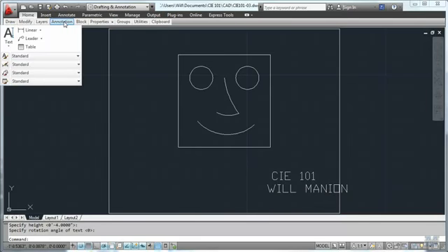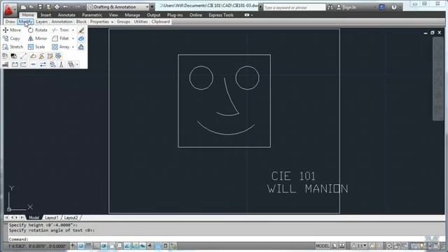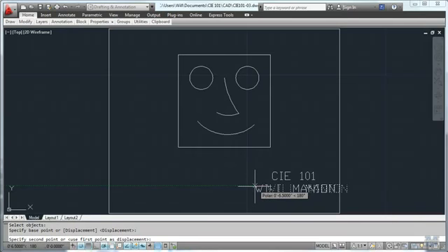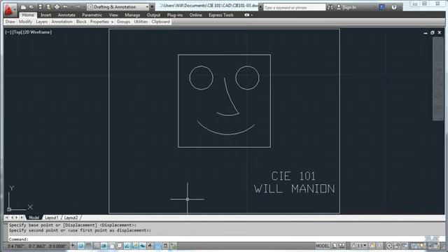So I guess I'm going to have to use the move to get that back on my screen. So let's go ahead and use the move tool this way. Select objects. I'm going to have to hit the enter key. That's the only object I want to move. Base point is where I want to start from. And then move it over a little bit so it kind of centers. Okay, pretty good. Now if you don't like this particular text, we can change that too.